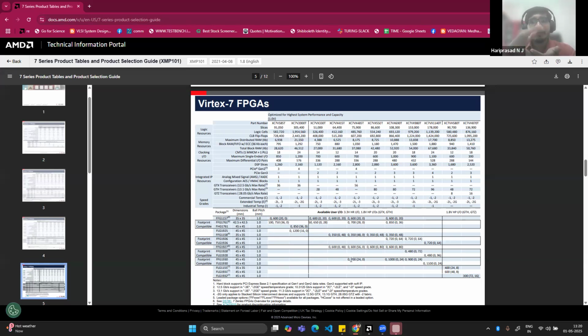So still your FPGA will power on. What we will do is switch off the device, take the temperature to -30 or -40 degrees, then try to power on. It should still power on, because let's say someone takes the device to Kashmir or Himachal or somewhere the temperature is negative. Your device is off, and when they power on, it should power up, right? That kind of testing we have to do properly.